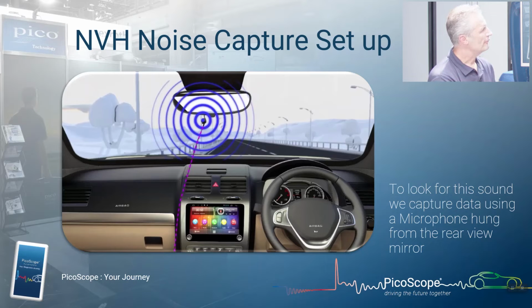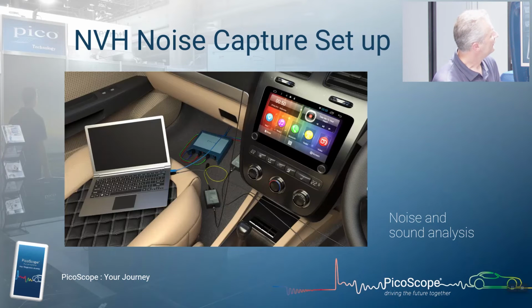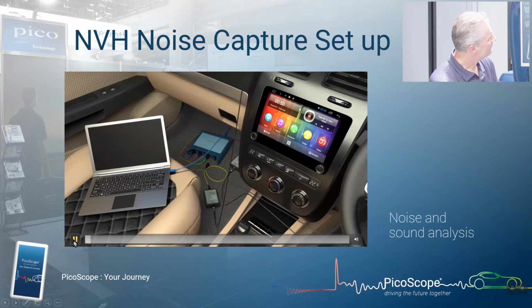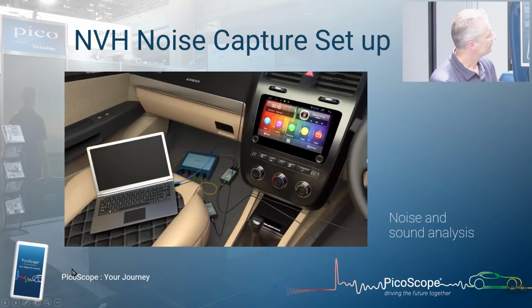We're going to put a microphone inside the cabin off the rear view mirror. If the driver is complaining of a noise right here, or he can hear it there, it may be from the door, then let's place the microphone in that vicinity, because microphone placement is essential. So here is our connection. We're going to utilise channel D. Why not? It's a spare channel, so we'll keep our 3-axis measurement and a microphone, as we'll demonstrate later on.